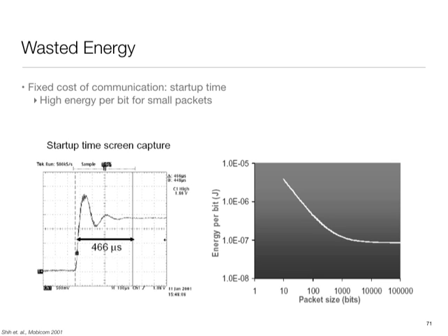So what you see often is that a lot of these radios for IoT type applications are really optimized for shorter packet sizes. 32 bytes, 64 bytes, these kinds of numbers are typical. Whereas when you're looking at your Wi-Fi or internet type things, these are 1500 bytes or even bigger jumbo frames. So we are operating in this regime where we have shorter packets, which has some advantages, but it also has the disadvantage of a higher overhead, which results as a consequence.